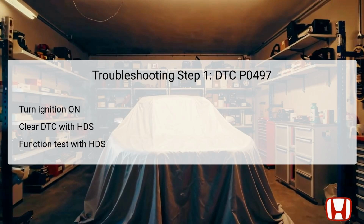After clearing, it's crucial to select the EVAP test from the inspection menu and perform the function test with the HDS. This test assesses the operability of the EVAP system and helps determine if the issue is consistent or intermittently occurring. If the result indicates that the system is functioning properly, further investigation is needed to check for potential loose connections or terminals affecting system performance. And the next troubleshooting step should be initiated.